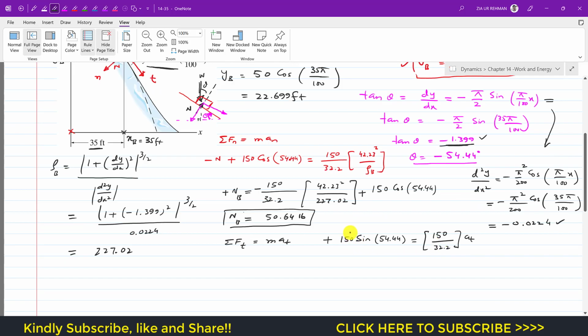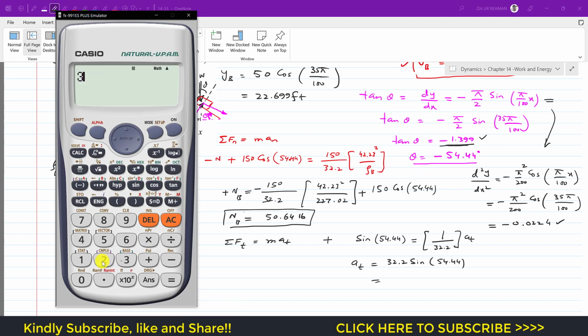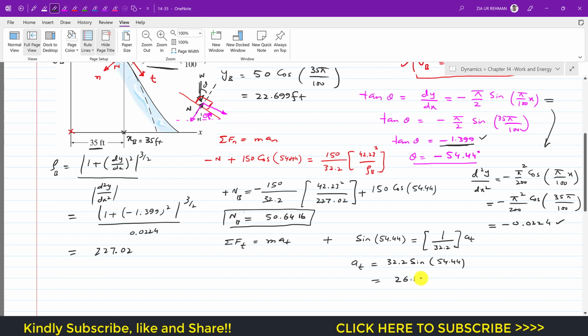If we divide both sides of the equation by 150, this will cancel out, and if I multiply both sides by 32.2, this is 1 divided by 32.2. So a_t from this equation is 32.2 sine of 54.44. So this gives us 26.19. So 26.19 feet per second square is the rate of increase in the speed.